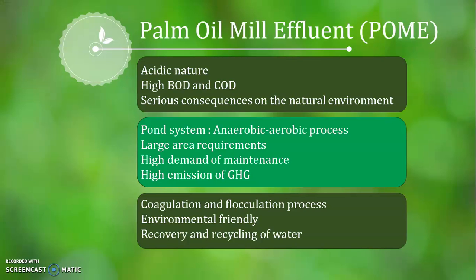Research background of POME. It is acidic in nature. POME has high BOD and COD levels. Biological oxygen demand is around 25,000 mg per liter, whereas chemical oxygen demand is 40,000 mg per liter. POME can create serious consequences on the natural environment.